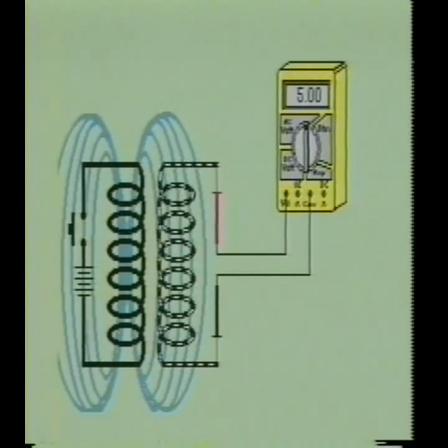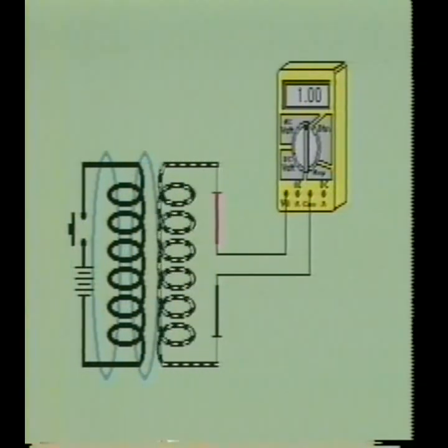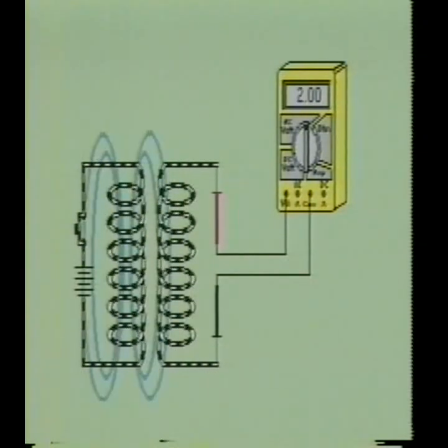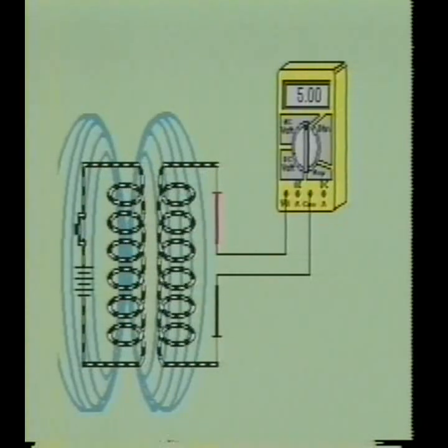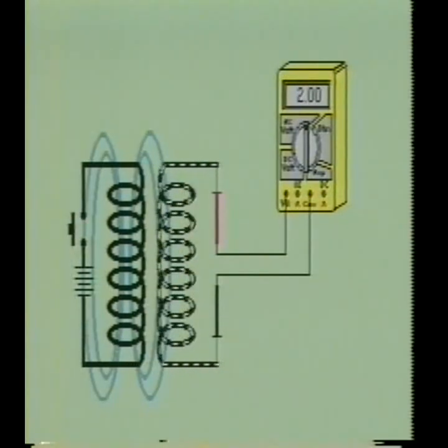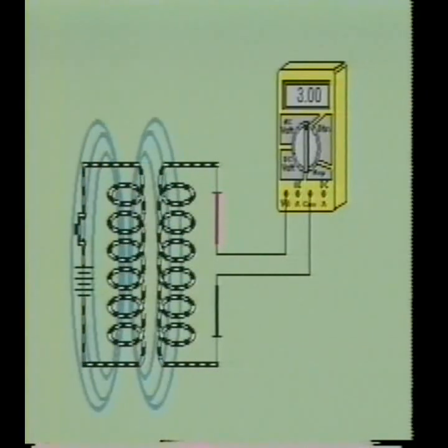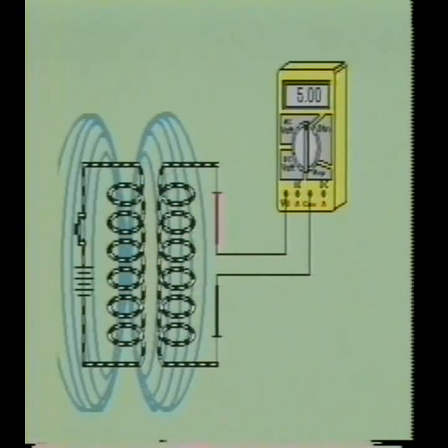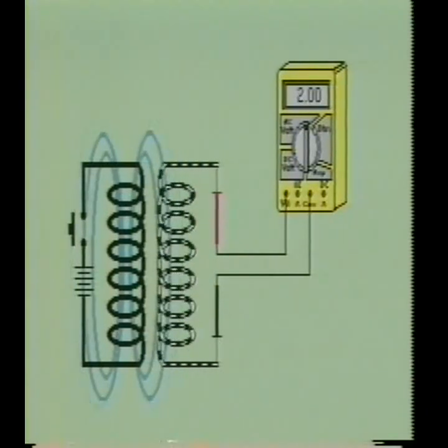If a switch in a current-carrying circuit is opened suddenly, there will no longer be any current to support the magnetic field and it will begin to collapse back around itself. As the field collapses inward, a voltage in the opposite direction will be induced. This voltage could also be called a counter-electromotive force, but it is usually known as a self-induced voltage. This self-induced voltage will be such that its polarity will be the same as the applied source voltage. Therefore, the voltage due to self-induction tries to maintain the current flow through the circuit.